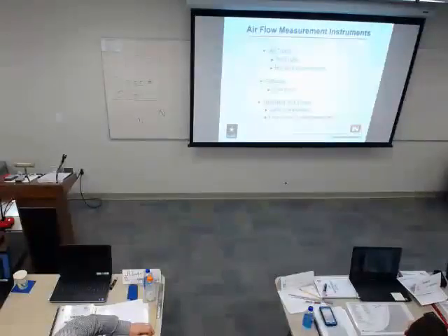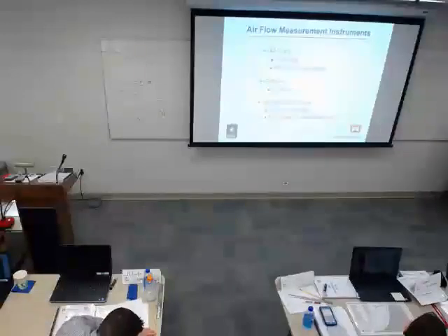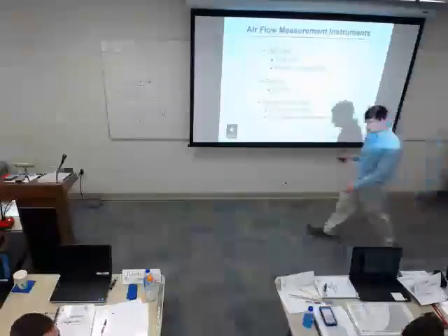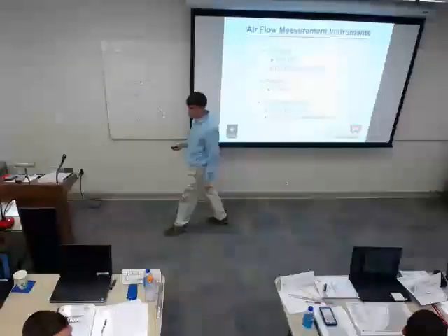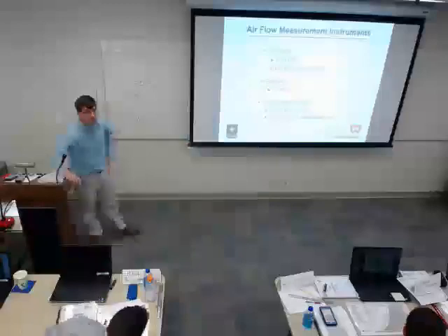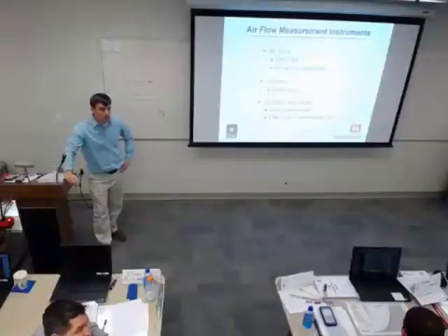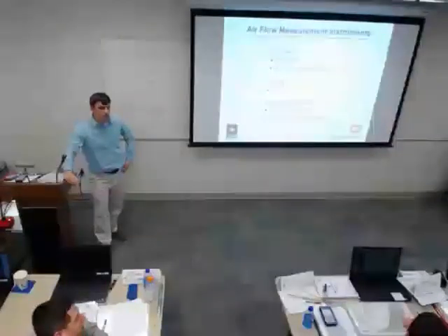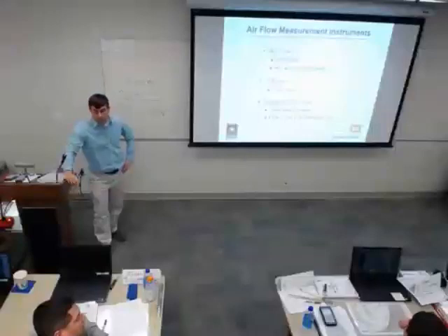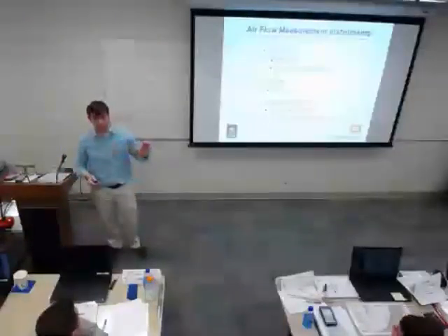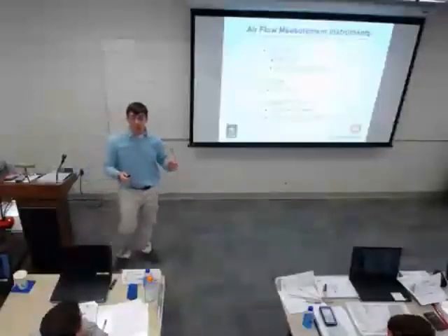With the flow hood, the hood catches all the air and brings it through. But on the anemometer, if the air is getting drawn into one side of the diffuser, that will actually happen inside, with the other amount coming out the other side. So you'll measure both amounts if you're not careful. You would not want to use that on a diffuser like this. You want to use it against a flat grill or register, or a coil inside of a unit.